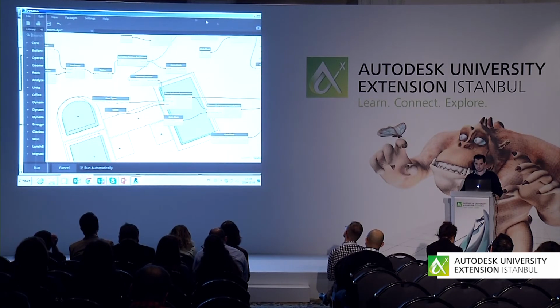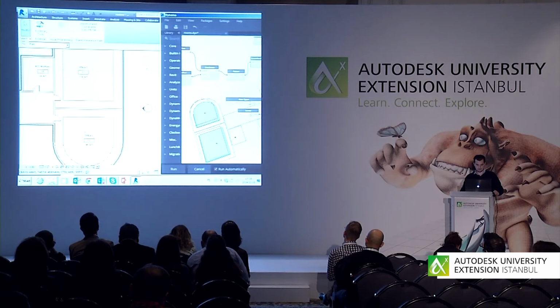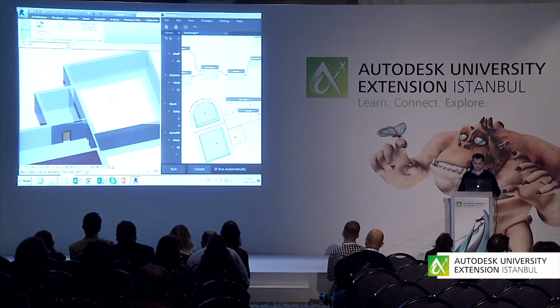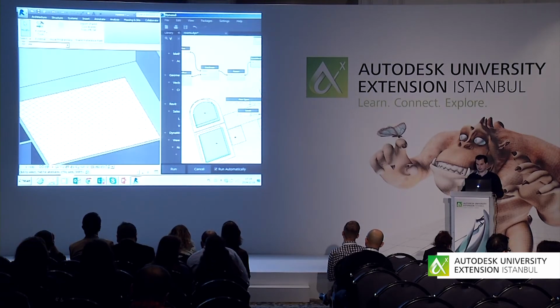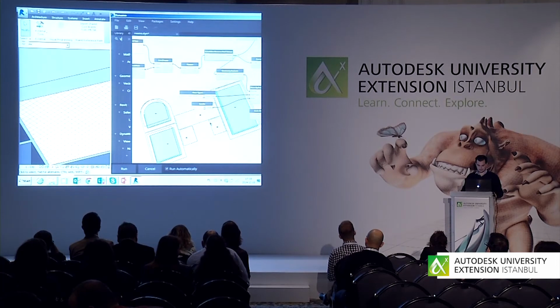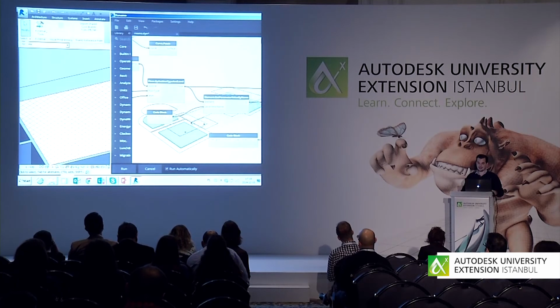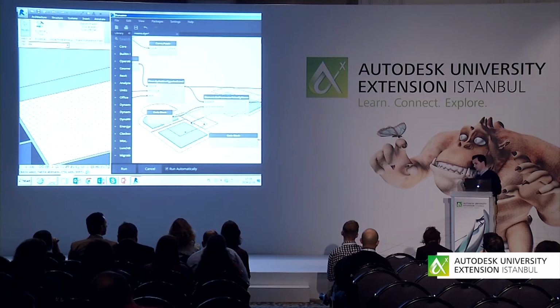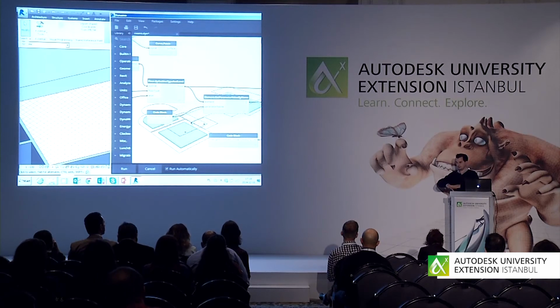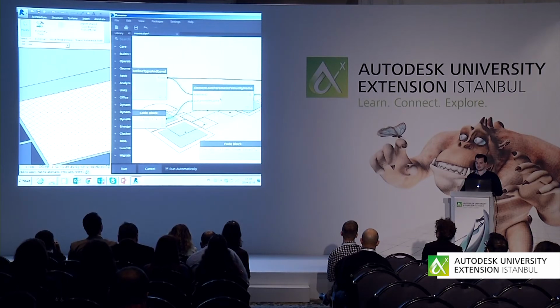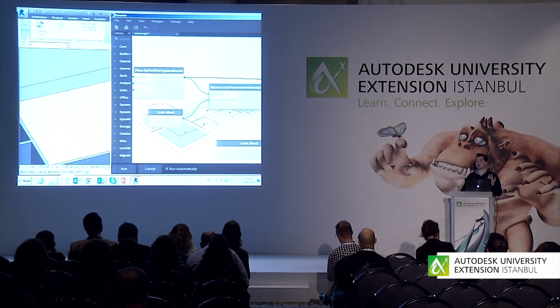And what will happen is that it has created these floors for me, the finishing layer of the floor. And what is also very useful is that since I do not want these floors to overlap, I can use the node called get parameter value by name, and I'm reading the thickness of my floor.